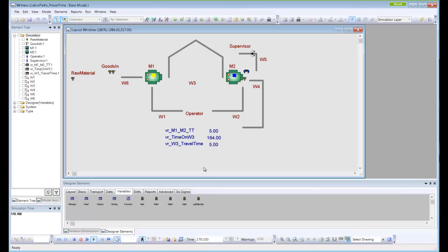Okay, very simple but very convenient, and certainly with quite a few models I do, I choose to have the travel time set explicitly from data in Excel, particularly if I'm trying to establish the takt time for operators moving around a small cell of machines.